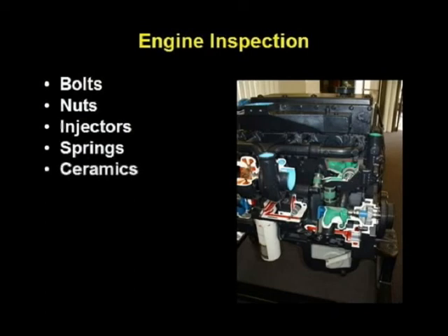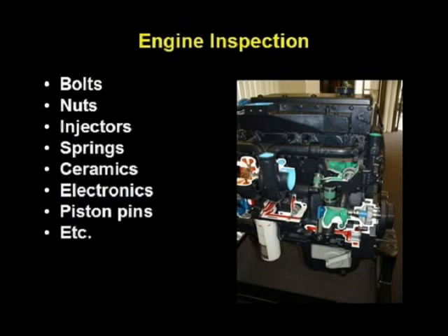Even ground ceramic parts are inspected by penetrant methods for cracks or chips. Electronic components have been checked by radiography for continuity of internal wires. Piston pins are checked for inclusions using ultrasound. I could go on and on about many other applications, but by now I think you get the idea.